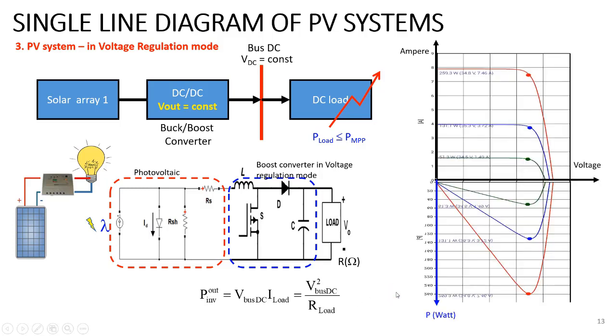With this Pout value, from the PV curve, we can identify two working voltage values, A1 and A2, each of which leads to a different related value of working current as shown on the IV curve.